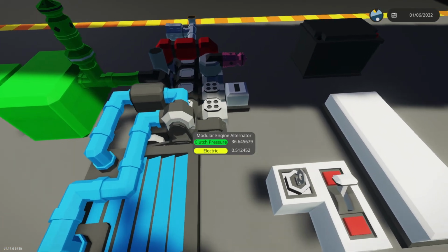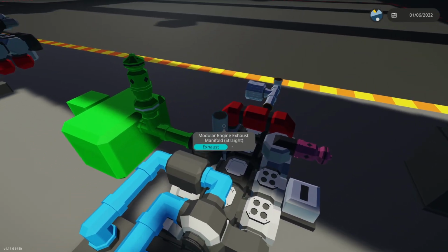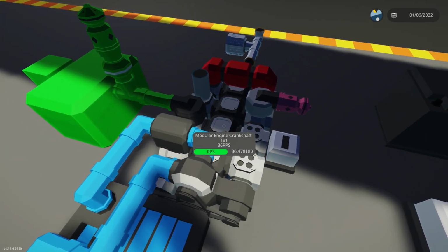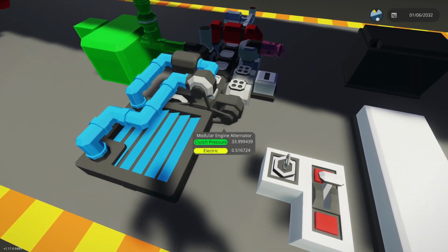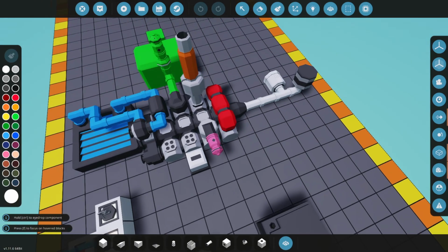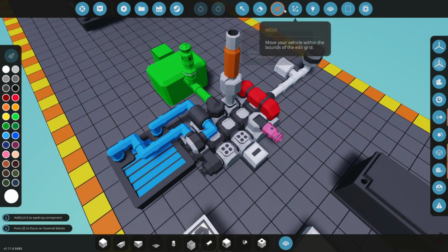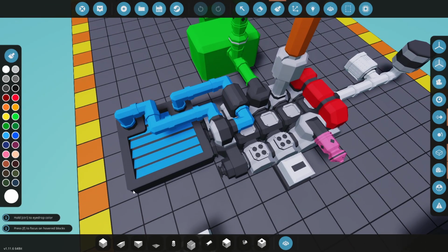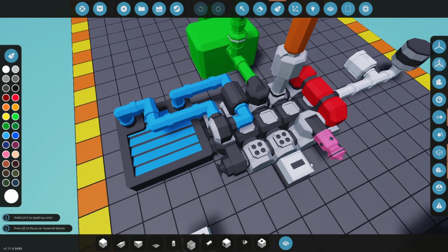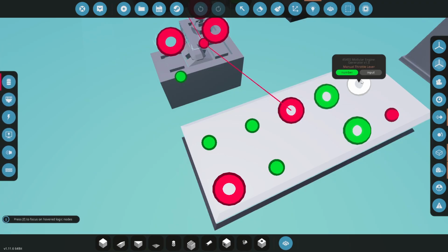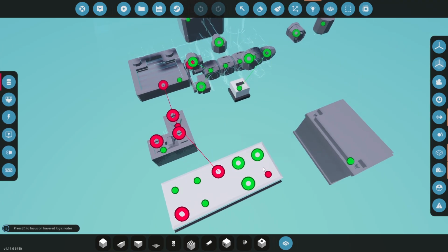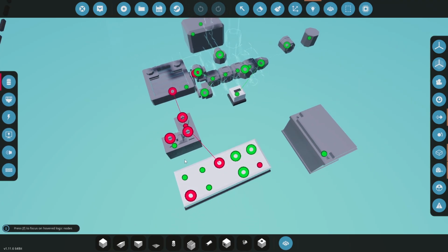And then what's going to happen is it's going to come to a point where obviously the exhaust is building up inside and it's just going to stall right out. It's not going to be able to do this forever. So like I said, either it is engine related, and by engine I mean the physical building of the engine, or it's microcontroller related. If you didn't connect something properly, I just opened up an old version and you see nothing is attached. So you have to make sure it's attached properly.